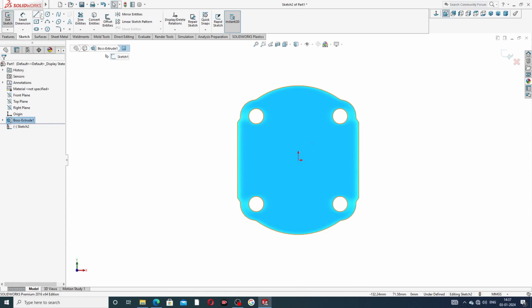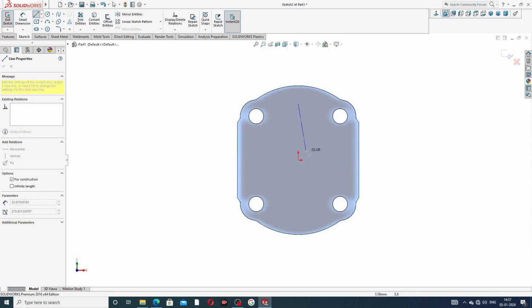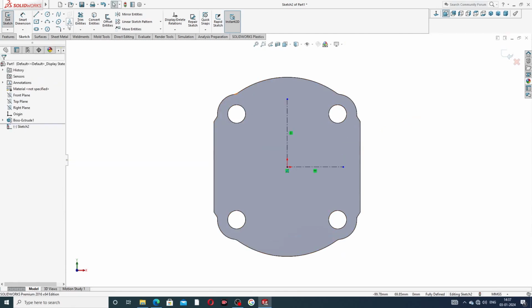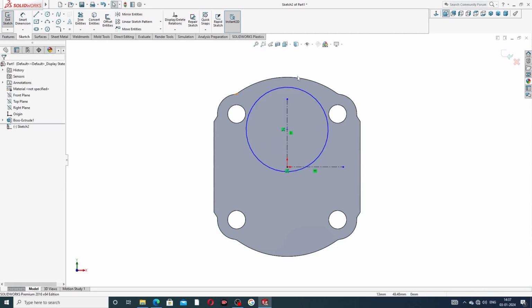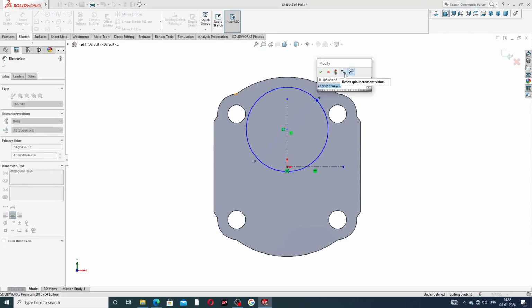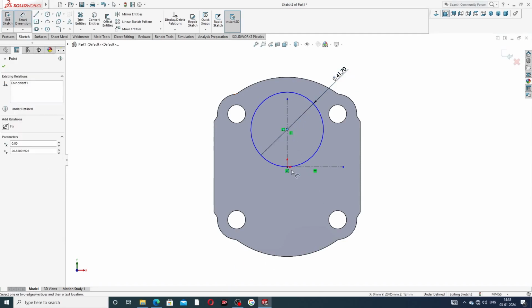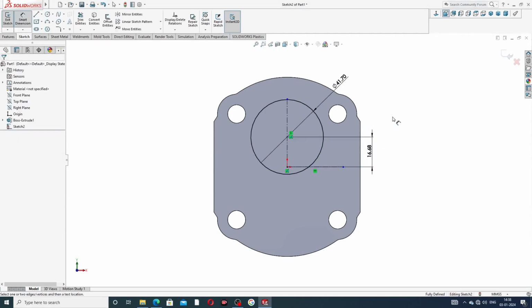And again drawing a construction line. This line is very important. Draw a circle above the origin, and draw a big circle, and this diameter is 41.7 millimeter, perfect, and this point to this is 16.68 millimeter.